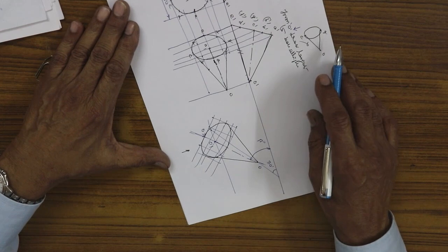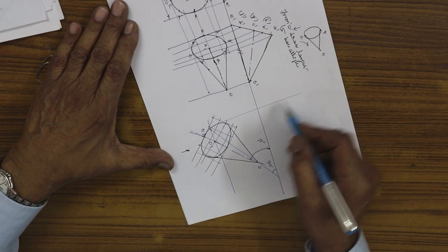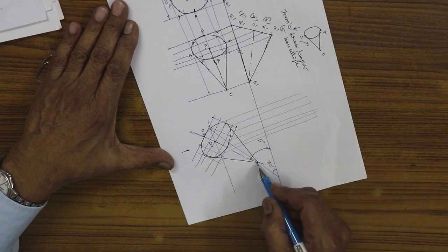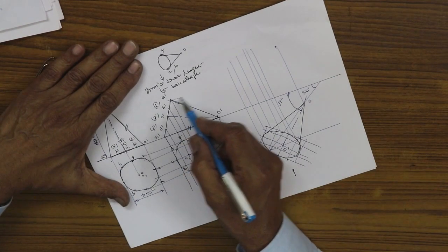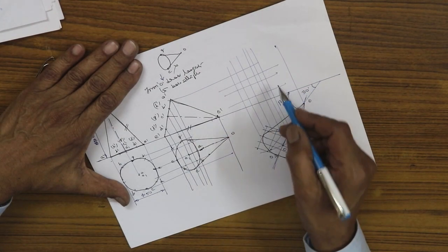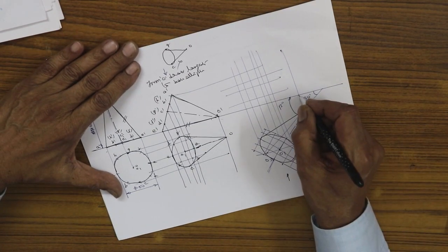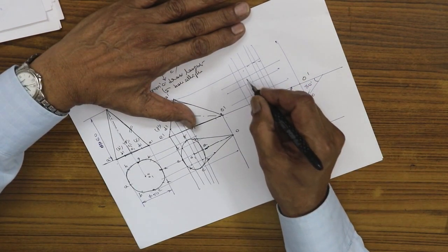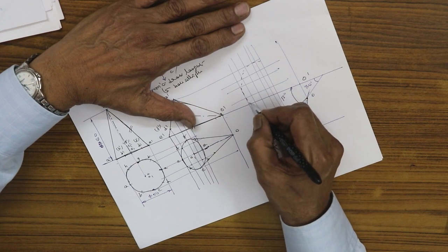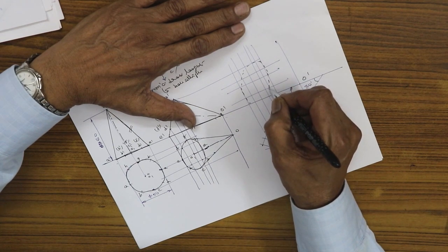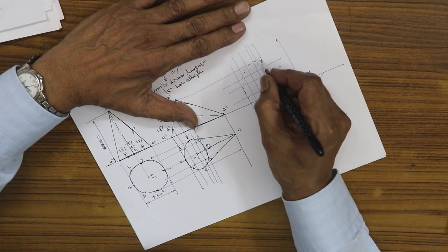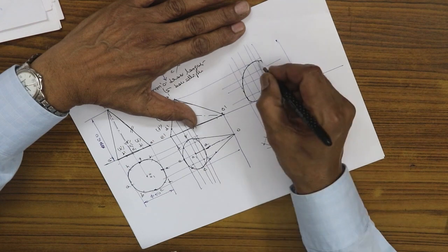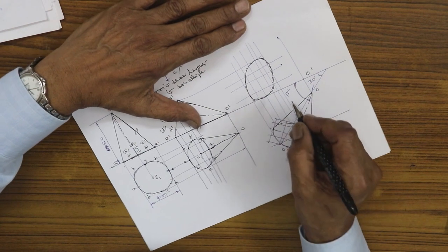Since I am just proceeding with freehand sketching, I'll project all the 8 points in this manner. Then the apex point here, and draw here the locus lines, all the 8 points locus lines. Get the point here. This point will be O dash. We get an axis, and you get an ellipse joining all the 8 points. Slowly, carefully, you join all the 8 points. From the front view, the base is nearer, the ellipse is fully seen.